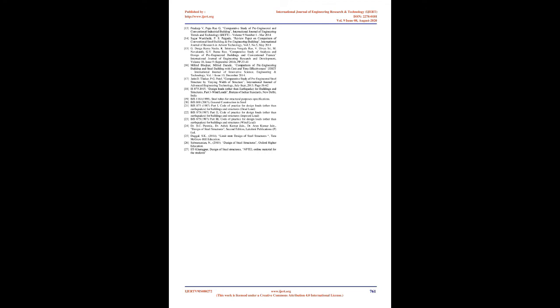7. Web-tapered steel portal frames construction reduces the weight of building compared to conventional steel structures. 8. It reduces the amount of steel requirement, and reduction in dead load reduces the size of foundation. 9. Web-tapered steel portal frames construction is 30 to 40% faster than conventional steel structures. 10. It provides good insulation effect and would be highly suitable for a tropical country like India. 11. Web-tapered steel portal frames is ideal for construction in remote and hilly areas.